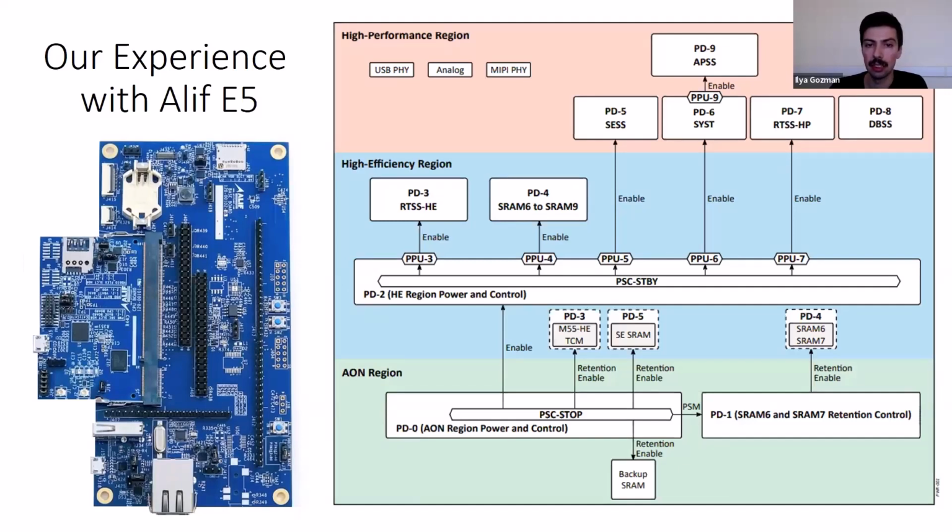Alif provides a powerful tool, Alif Conductor, which allows us to configure the board for specific tasks and usage scenarios. One more advantage of our fine-tuning platform is the ability to repeatedly measure the power consumption of every step of the model evaluation workflow, such as awaiting data acquisition, pre-processing, inference, either on NPU or CPU, and post-processing.